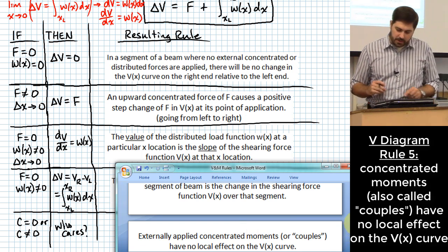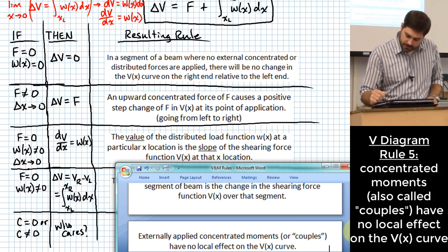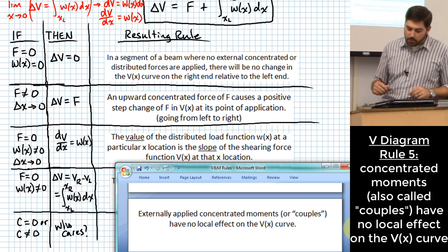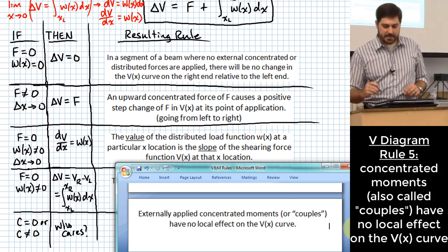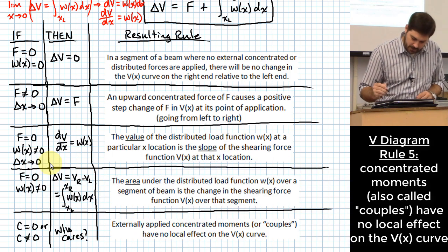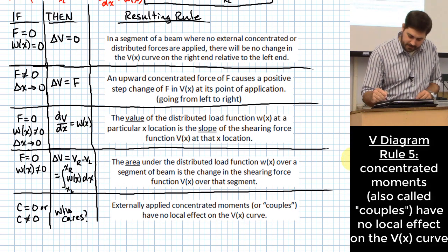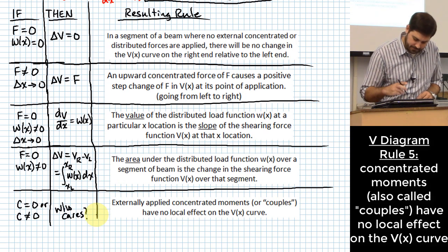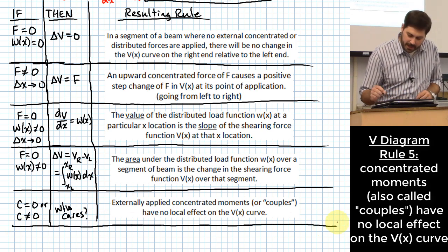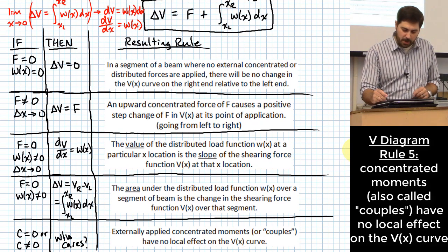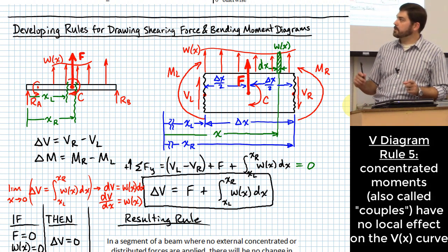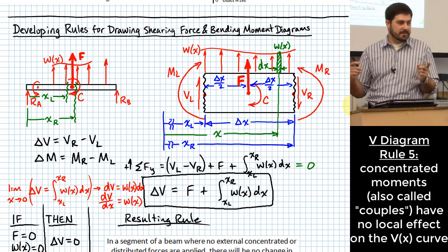Externally applied concentrated moments, also called couples by the way, have no local effect on the V(x) curve. I said this kind of carefully. What do you think I mean by local effect? I have to be careful here, because if I apply a concentrated moment on my original case, it will affect my reaction forces RA and RB.